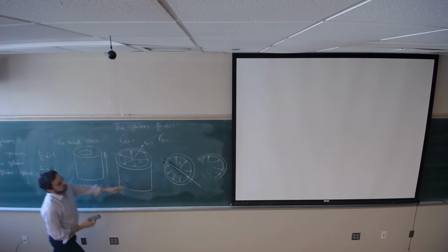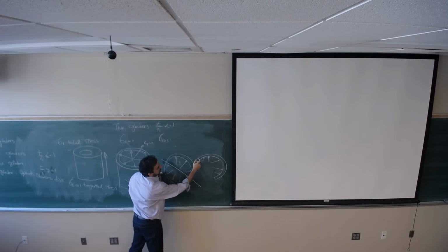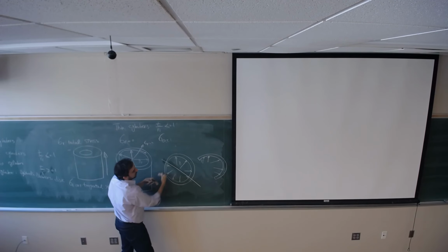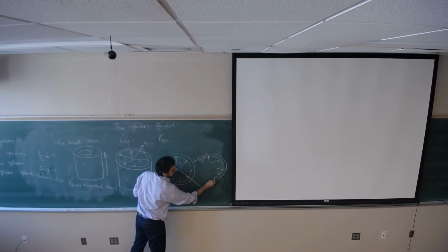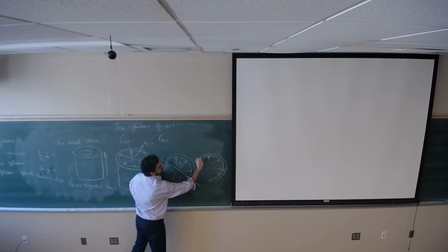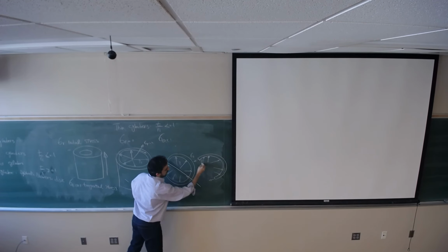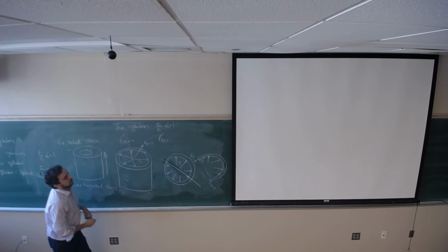So due to this internal pressure, this pressure is going to separate these two halves. But it's going to make some stresses on this thickness that we call sigma t or sigma theta, because it's perpendicular to this line. So sigma t or sigma theta is going to develop in these two thicknesses. We are going to find this value.